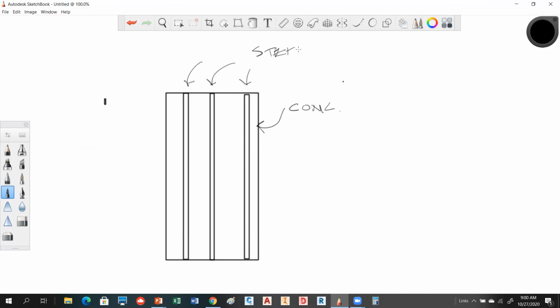So those two materials, notice they're parallel. They respond differently because, again, you have an E of steel and you have an E of concrete, and they're not the same numbers. Interestingly enough, though, what we normally do in these problems is say that the L value in this type of problem is going to be the same.